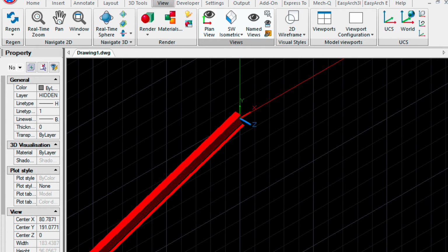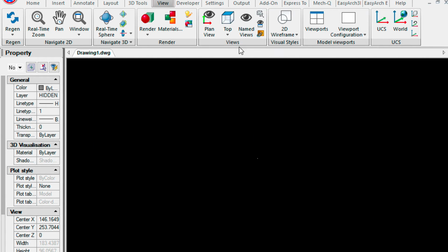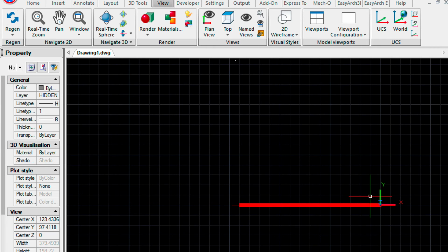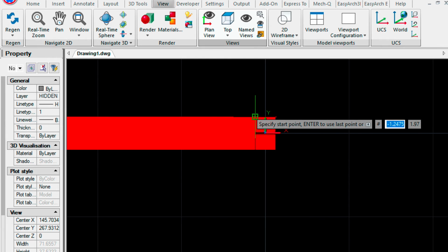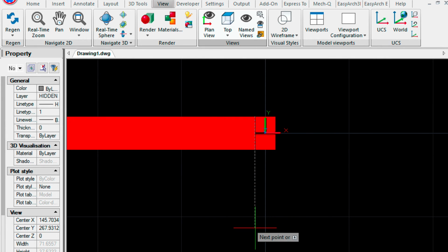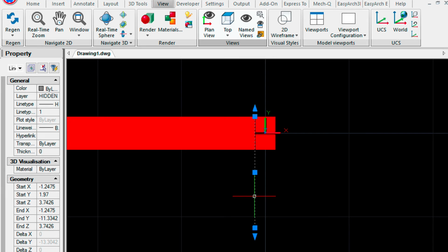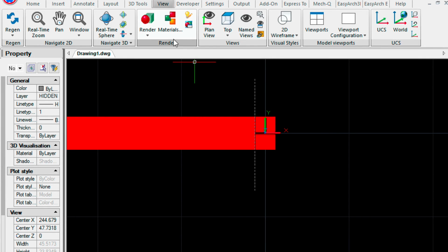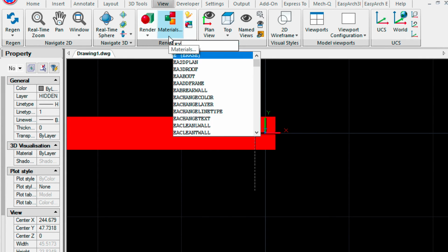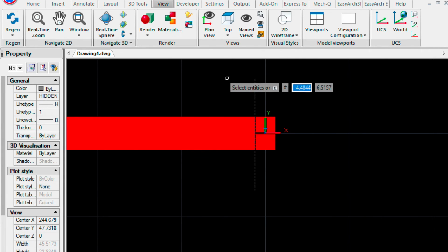Now, on this roof, if we want to trim this so that it's straight up and down, in other words, if we want to join another roof to the other side, we're going to pick the ridge there on the left. I'm going to create a line snapping right over the ridge, and then I'm going to move this up just a little bit, and extrude by typing the extrude command. I'm going to extrude this line up 3 feet from the ridge.